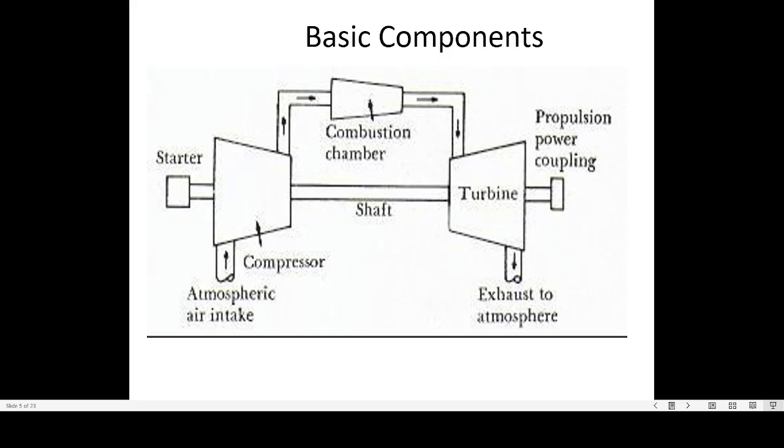This particular block diagram shows the arrangement for the gas turbine cycle. Here we have the air compressor, and this region shows the atmospheric air, the surrounding air, that is drawn into the compressor. High pressure air leaving the compressor enters the combustion chamber. We burn the fuel. Gases are then admitted into the turbine, which performs the mechanical work after the expansion, and the gases are exhausted to the atmosphere, to the surrounding.